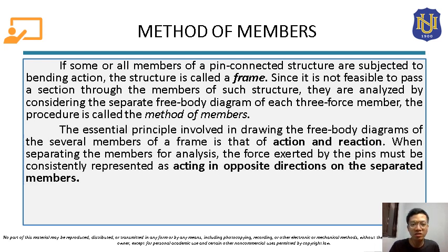The essential principle involved in drawing the free body diagrams of the several members of a frame is that of action and reaction. When separating the members for analysis, the force exerted by the pins must be consistently represented as acting in opposite directions on the separated members. So it is important that we are consistent with the directions of the reaction forces involved in the free body diagram of each member.